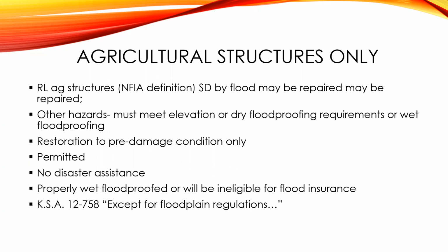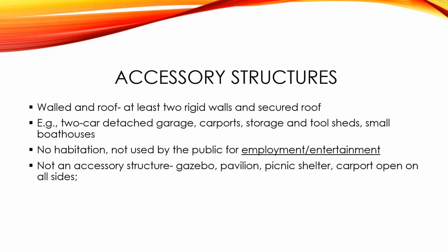And FEMA has really clarified what they mean as far as being allowed to be wet floodproofed. Again, accessory structures, it's the same thing. We're talking about actual structures that are walled and roofed. So having at least 2 rigid walls and a secured roof.